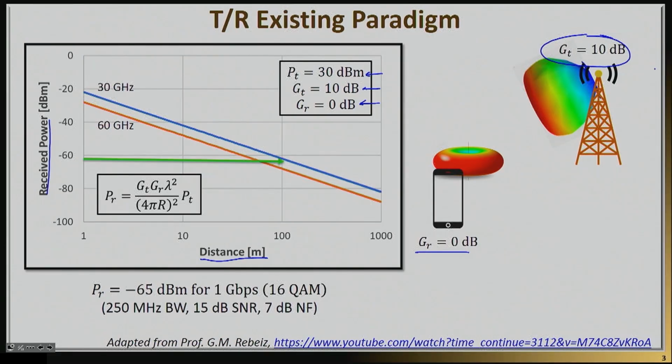A lot of times you will see gains in cell phones down to -6 dB, -7 dB, and so on. But nevertheless, let's assume it's about 0 dB. And then I'm assuming that I need to receive roughly a 16 QAM modulation scheme, which we did cover in this class. And for that one, for a 1 gigabit per second data rate, I need to receive roughly -65 dBm.